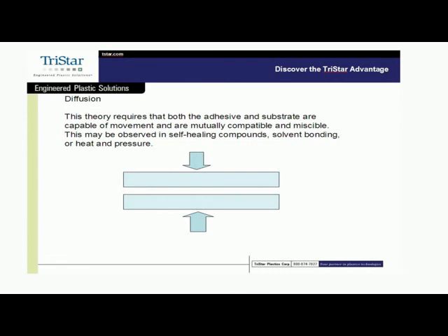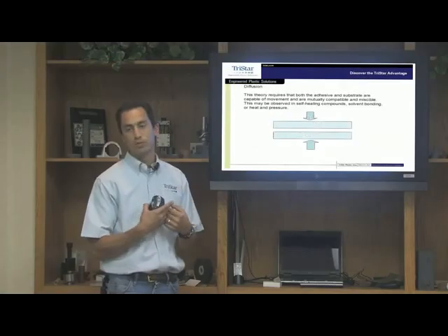Now it takes energy to get those apart, and you definitely have enough energy just in your hands to separate that material, but it appears at the molecular level that it has healed itself, so that slit no longer exists. But in this theory, really where we apply our technology is that we interrupt that interaction. We take all those long, loose polydimethylsilicone polymer chains and we chop them up so that the diffusion theory doesn't work anymore.